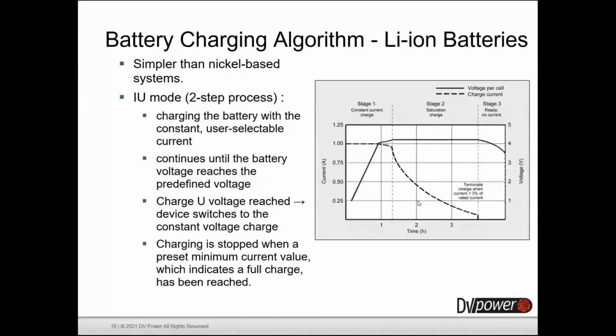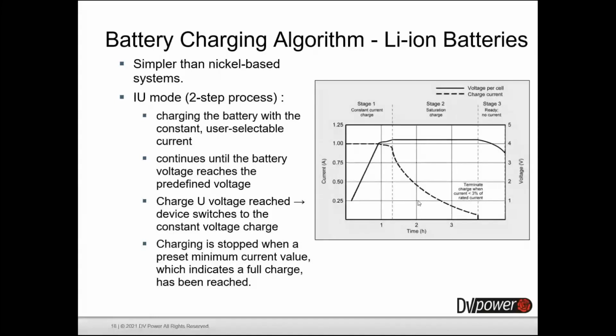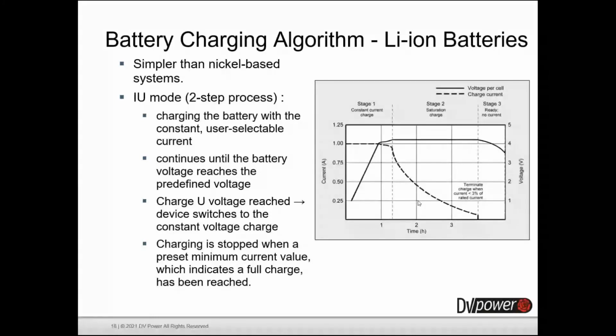You know, they can set on fire if overcharged. So the so-called miracle chargers that can be found online that promise to prolong the battery life and gain extra capacity of lithium-based batteries with pulses and other gimmicks, that doesn't exist. So lithium-based batteries must be strictly charged according to manufacturer's recommendations. They don't accept overcharge. You can set the batteries and yourself on fire if doing so.